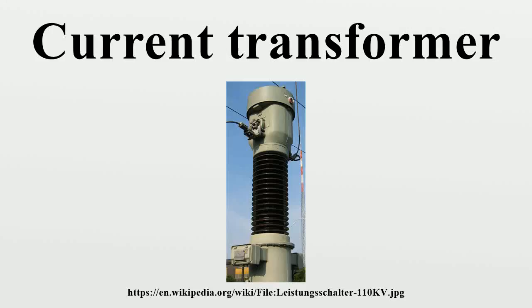A current transformer is an electric device that produces an alternating current in its secondary which is proportional to the AC in its primary. Current transformers, together with voltage transformers or potential transformers, which are designed for measurement, are known as instrument transformers. When a current is too high to measure directly or the voltage of the circuit is too high, a current transformer can be used to provide an isolated lower current in its secondary which is proportional to the current in the primary circuit.